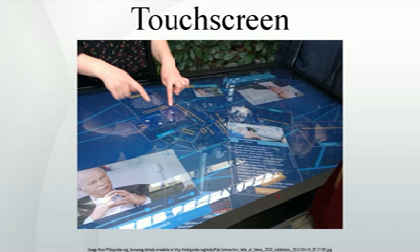Infrared acrylic projection. A translucent acrylic sheet is used as a rear projection screen to display information. The edges of the acrylic sheet are illuminated by infrared LEDs, and infrared cameras are focused on the back of the sheet. Objects placed on the sheet are detectable by the cameras. When the sheet is touched by the user, the deformation results in leakage of infrared light, which peaks at the points of maximum pressure, indicating the user's touch location. Microsoft's PixelSense tables use this technology.